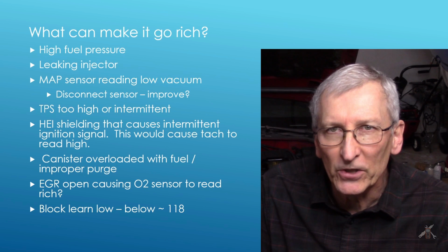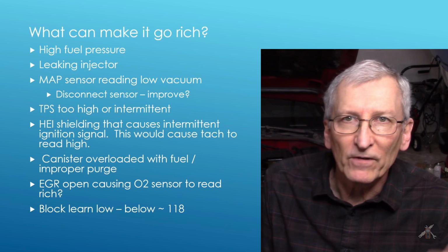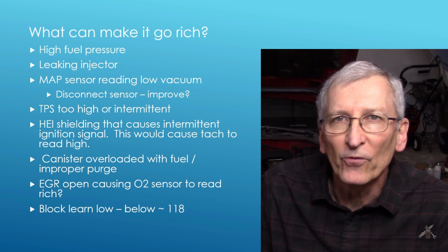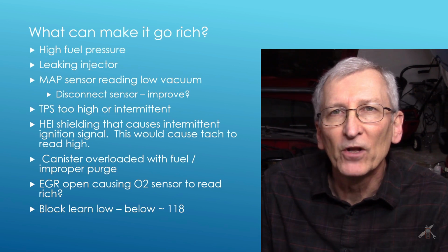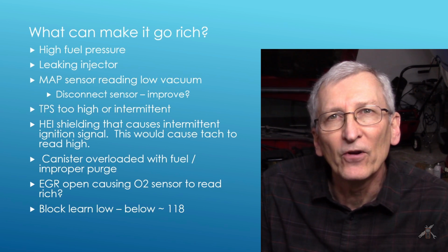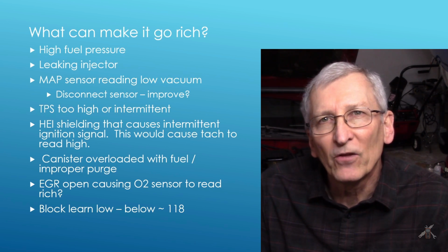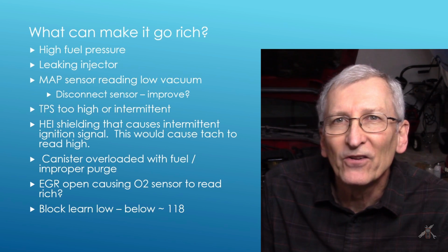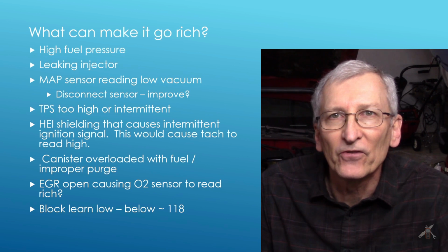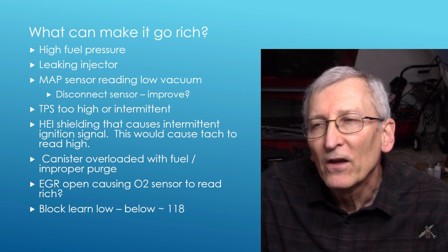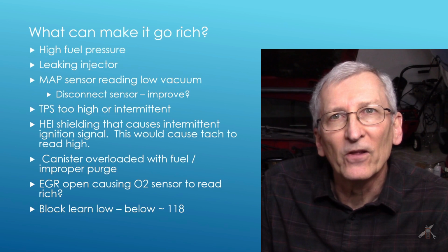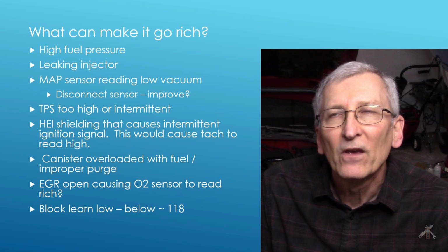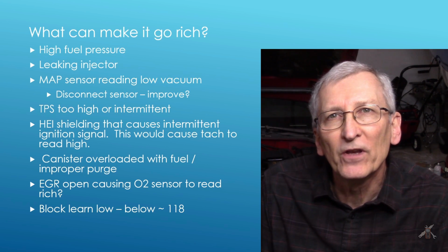Is the diaphragm leaking? I'll tell you, I had one just a couple of months ago, a nephew of mine, who lives quite a ways away, and over the period of months we were troubleshooting one of his engines over the phone. He was telling me symptoms, and he found it, I didn't. I just kept pointing him in different directions, and he'd go dig in. And he had a bad fuel pressure regulator. The diaphragm was bad, and it was bleeding fuel, and it would bleed fuel when the engine was turned off.